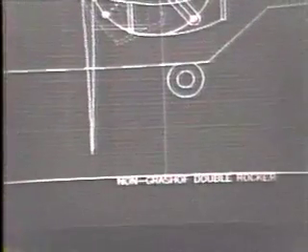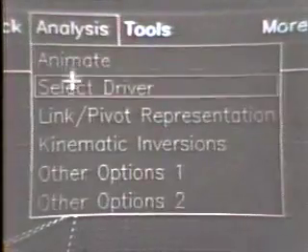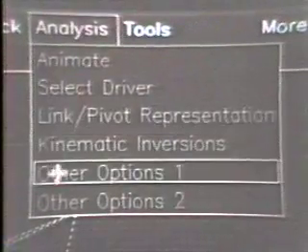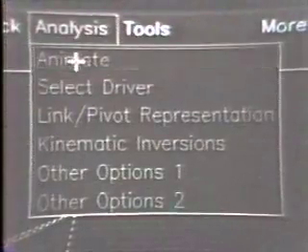Here the designer has picked a 2nd moving pivot. As the designer scans through the possibilities for the 2nd moving pivot, the computer shows the entire linkage in all its design positions. It indicates the Grashof type for the linkage, and if desired, it also displays such things as the transmission angles or the coupler curve for the mechanism.